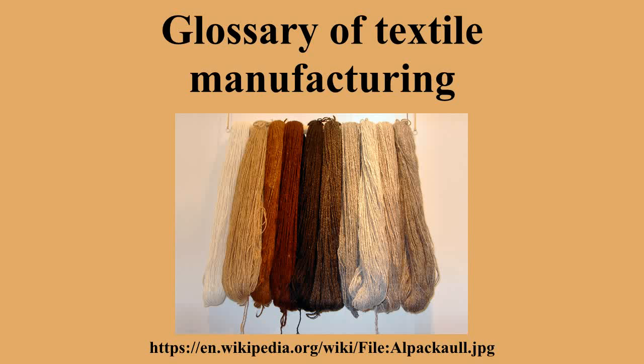Barathea. Barathea is an indistinct twill or broken rib, usually a twilled hop sack weave, with a fine textured, slightly pebbled surface, often of silk or silk blended with wool, used for neckties, women's fine suits and coats, men's and women's evening wear. Batik. Batik is an Indonesian traditional word and refers to a generic wax-resist dyeing technique used on fabric. Bedford cord. Bedford cord is a combination of two kinds of weave, namely plain and drill. It is a durable fabric that is often used in upholstery or outerwear.